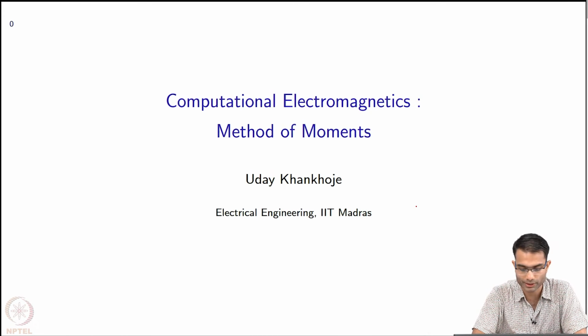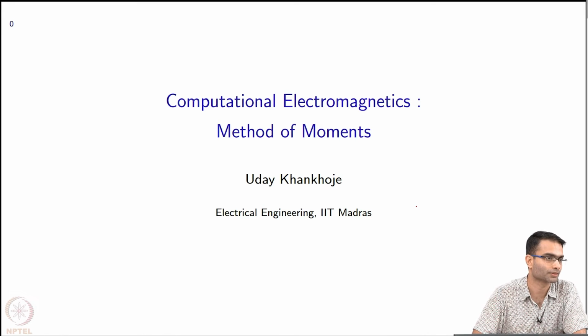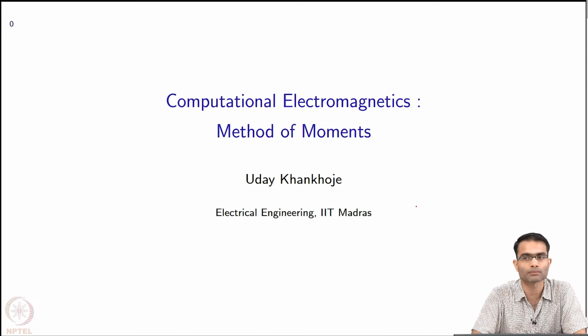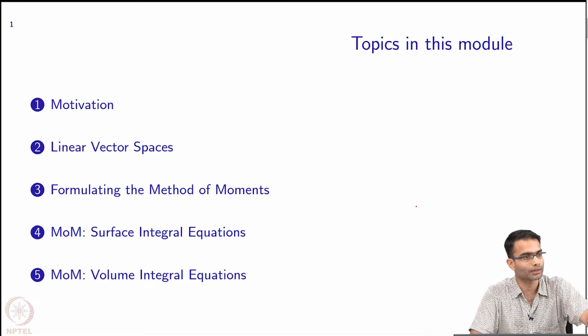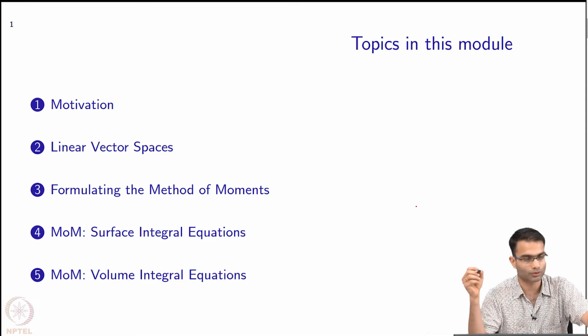So, this module is going to be about the method of moments, which is the name given to the way in which we solve the integral equations. So far we have seen one simple example of integral equations, which is the wire with the surface charge on it, and we wanted to find out the electrostatic potential. The second thing that we formulated was the surface integral equation, and we want to find out now how we solve this.